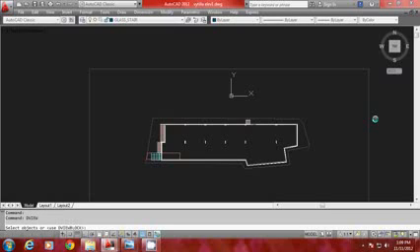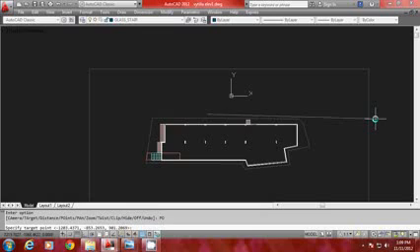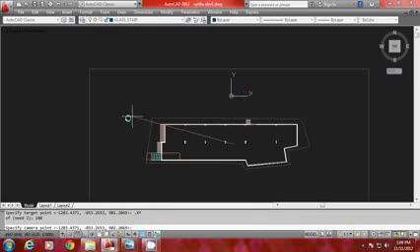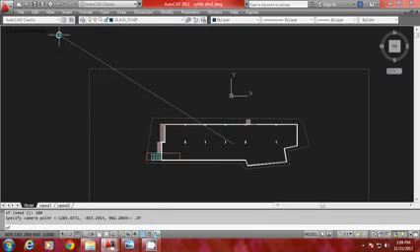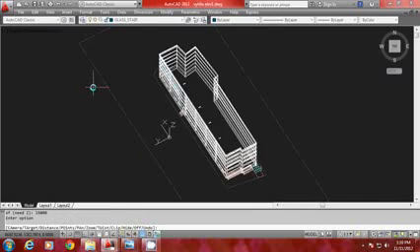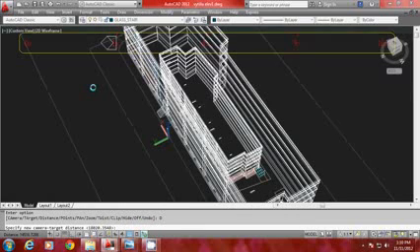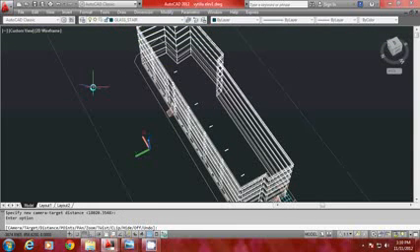So I'll go to dview command and I'll select the objects, and I'll go to points option. When I'm asked to specify the target point, I'll use point filters. I'll type .xy of. I'll pick a point over here, and I'll give a height of say 100 units for Z. And when I'm asked to give the camera, I'll specify .xy of. I'll pick a point over here, and I'll give a height of the camera as 15,000 units. Now you can see that the target and the camera are at different elevations, and I'll go to distance option and just give an enter to generate a perspective.